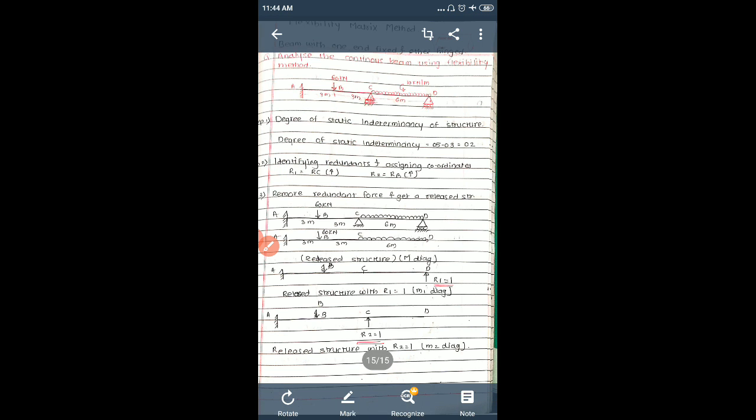Now we are going to cut the sections, and where we get any point load or any change in the coordinates or variable, we are going to consider those spans separately. So we have 3 sections that we have to consider separately.